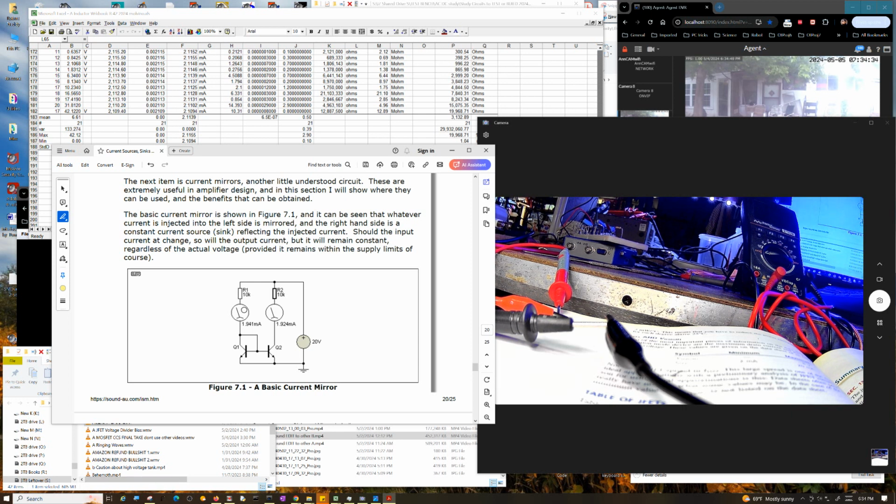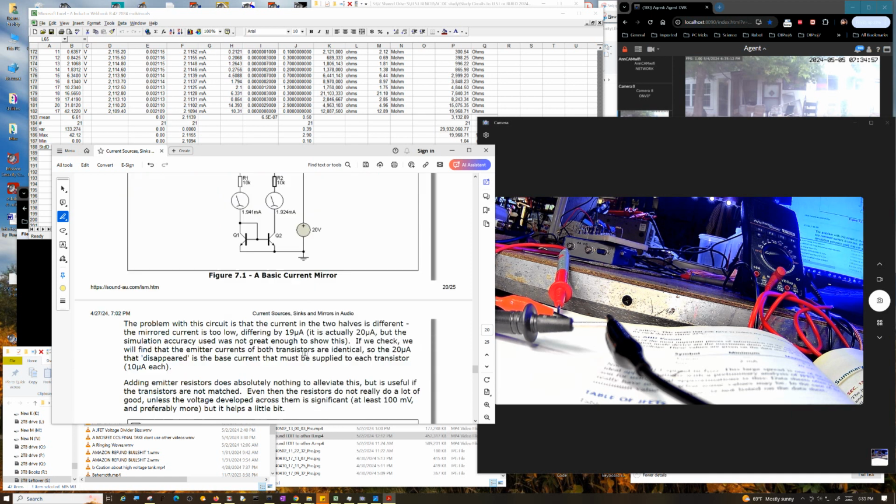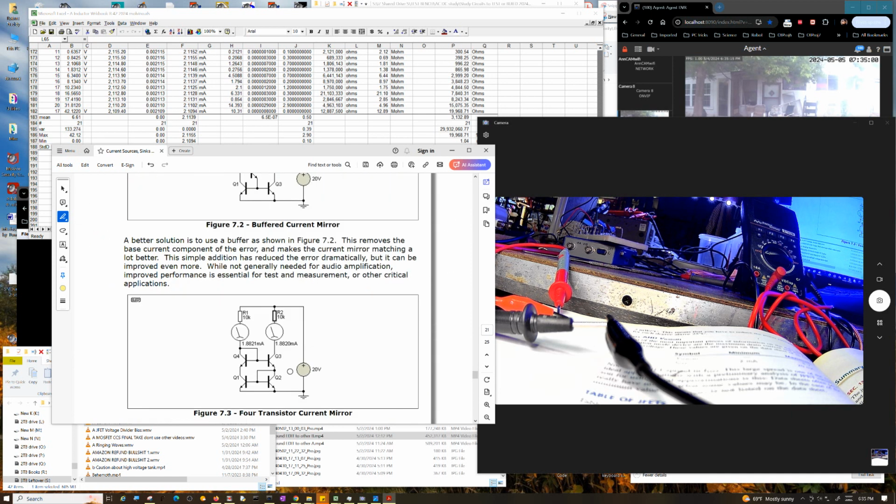But yeah, you might be able to use an op amp, put a little 3.3K resistor in it like I did in my circuit, and then have that set up as a unity gain non-inverting amplifier, and have a DAC hooked to that, so you could actually make a computer controlled constant current source, because this still acts like a constant current source. And I would imagine one of these more elaborate ones down here may even do a better job. So that's just food for thought if you needed a computer controlled constant current source that operates at a substantial voltage.